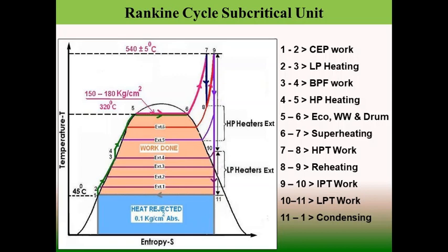So naturally we find that, though in this cycle both points 5 and 6 are present in the boiler drum, point 5 represents the saturated water and point 6 represents saturated steam, and the passage in between represents the addition of latent heat within the water wall tubes.